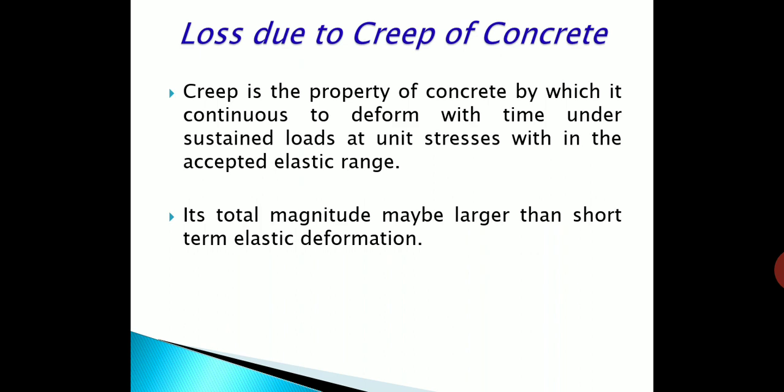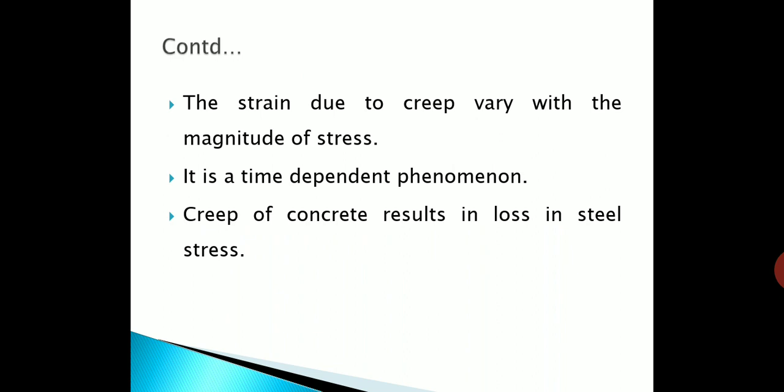member. The total magnitude of the loss of prestress due to creep may be even larger than that due to the elastic deformation. Hence, the creep factor has to be considered and given due weightage while calculating the losses in prestress. The strain due to creep varies with the magnitude of stress. It is time dependent. Creep of concrete results in loss in steel stress.